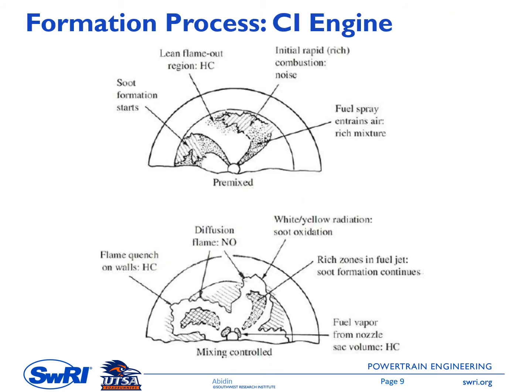Next one is the pollutant formation process in the compression ignition engine. As you have learned in chapter 10, we have a non-premix combustion process in the compression ignition engine. The combustion process period can be split into two periods. The first one is what's called the premix period, that is followed by the mixing control period. And this premix period occurs right after the ignition delay period.